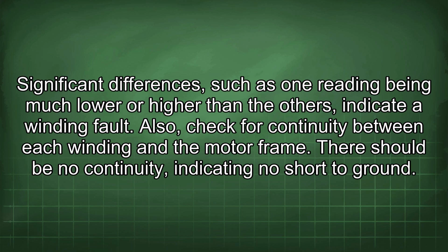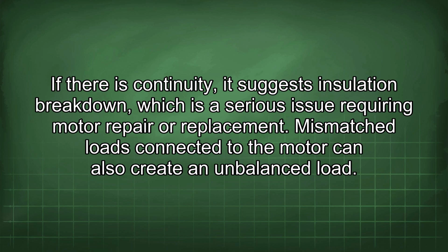Also, check for continuity between each winding and the motor frame. There should be no continuity, indicating no short to ground. If there is continuity, it suggests insulation breakdown, which is a serious issue requiring motor repair or replacement.